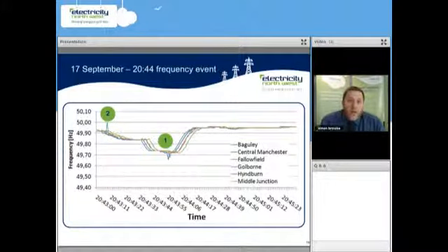It's only actually done that on 2 sites, but you have to remember that this is the actual measuring. All sites did trip, and the Siemens device did see that the frequency had fallen below 49.7 Hz at all the sites. So it's purely down to slight errors due to the measuring equipment fitted. We've also highlighted at number 2 a slight peak, and again that's the same issue. It's down to the measurement scanning or sample rate, so it's not expected that that site did actually peak at 50 Hz.